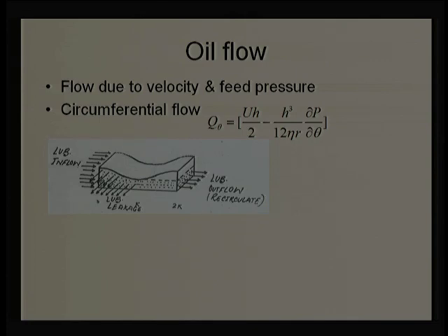We want to estimate temperature so that we can modify viscosity, and properly estimate the load carrying capacity of the bearing, as viscosity is going to affect load, and temperature is going to affect viscosity, and friction is going to affect temperature, and this is a common chain.